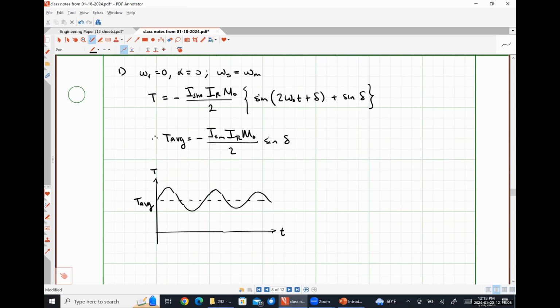So a system like this is perfectly acceptable if we're dealing with a very small motor because we're effectively saying we don't care if it's inefficient. So this would be like a single phase synchronous motor. But if we wanted something to do large industrial work, we would probably use a three-phase system because in a three-phase system, the amount of power that's being supplied to our motor is effectively constant, which means our torque will also be effectively constant, which means we won't have all of this vibration and all that kind of stuff that a single phase machine would have. So we can see here that we are developing some amount of average torque, but dependent on the situation, this might not be good enough. And so we might have to increase the level of complexity and go from a single phase machine to a three-phase machine in order to smooth our torque out and our power relationships and all of that kind of stuff out as well.